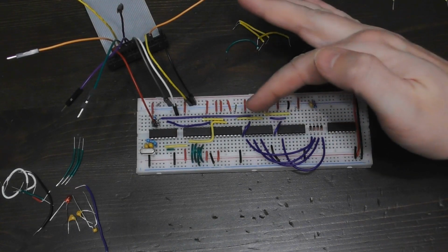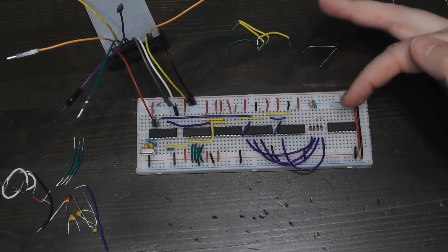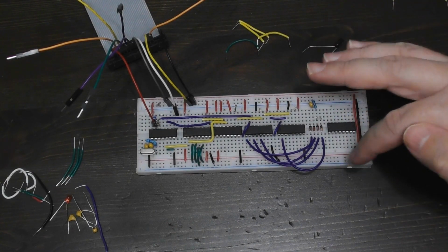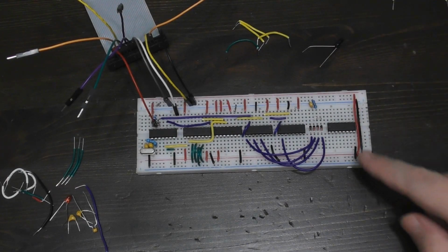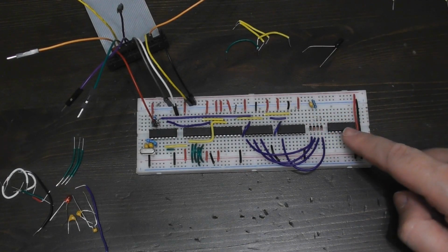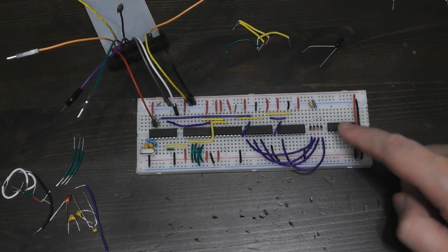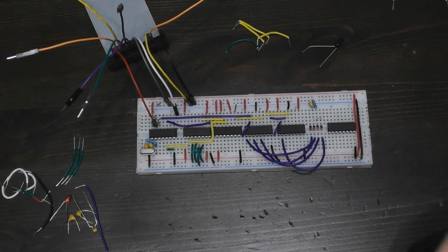After another 16 pulses on the reconstructed clock, the terminal count goes high again, and that's exactly the right number for the next byte of data to be received. So once the address mark has triggered this, it can just keep running forever, counting 16 ticks at a time, and every 16 ticks it will tell the CPU that there's a new byte of data to read.